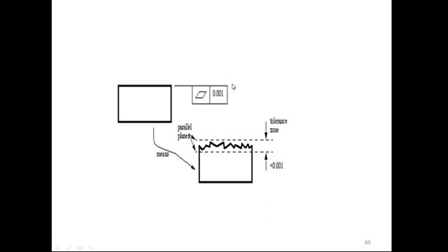So the interpretation of this is given here. See friends, every surface is in a zigzag manner. When you see it at a microscopic level, you will observe that it is a zigzag manner. So we want to define the peak and valley dimension, the top and bottom of this. When you measure across this, that is the tolerance value given, and it must be within less than 0.001, that is 0.001 mm we can say. So this flatness must be within this value. Here the range is given, so your flatness must be within less than 0.001. This is the meaning of this flatness symbol.